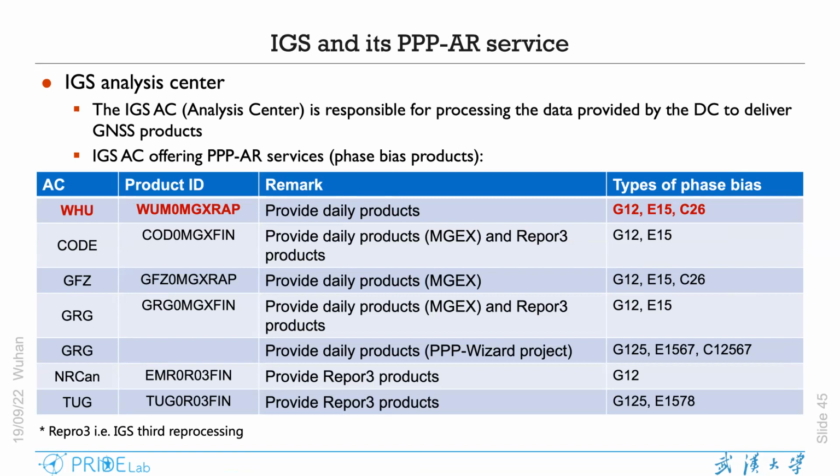So actually, what you get from your processing with low-cost receivers and low-cost antennas will be with respect to your phase centers rather than with respect to your antenna reference point. So you have to make sure that what you've got is actually the position of your phase center rather than any ground mark of your stations.